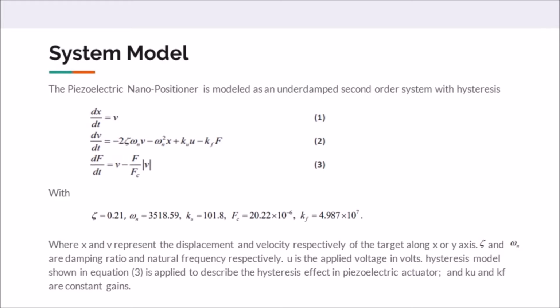In this slide, we see the differential equations that were provided to us for the system. Building the differential equations requires a thorough understanding of the system and how it behaves. Please note that all nonlinear equations needed to be linearized before proceeding with designing the controllers. This is because we cannot use any linear control theory on a nonlinear system.